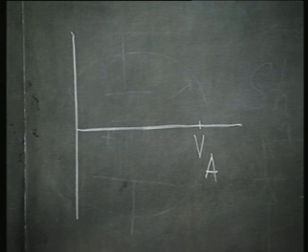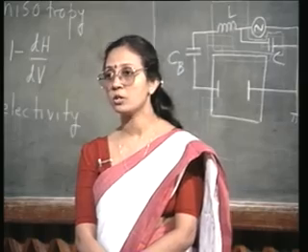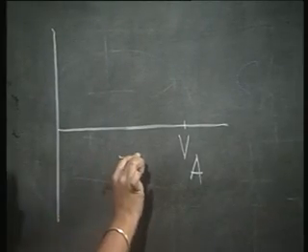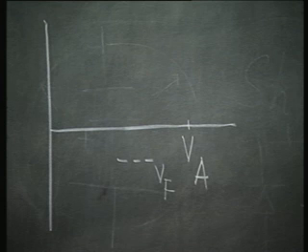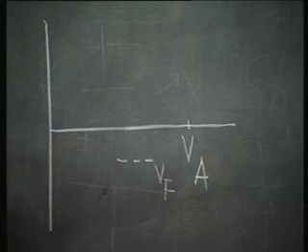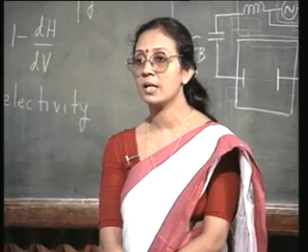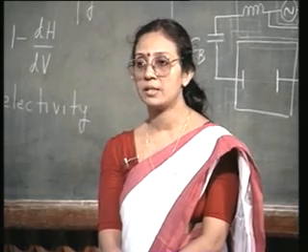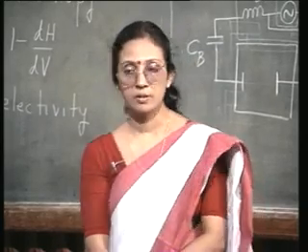I have told you that if I put any insulating surface inside this plasma, it is going to eventually acquire a small negative potential called the floating potential. So, this is the floating potential point, negative with respect to the grounded anode. Any insulating surface you place inside the plasma is going to acquire a negative potential. The glow, the central portion of the plasma, the potential of which I have referred to as Vp, is going to be positive, because it is comprised of positively charged ions.